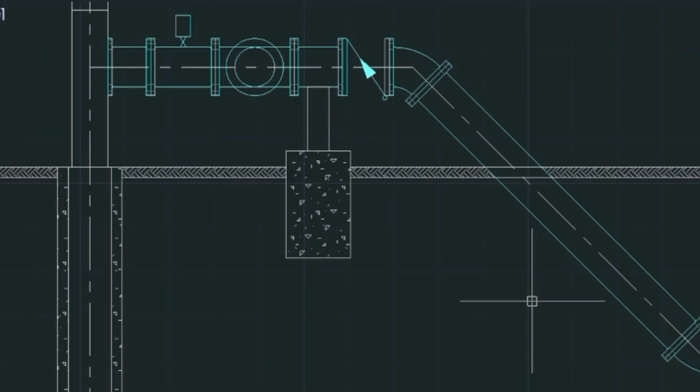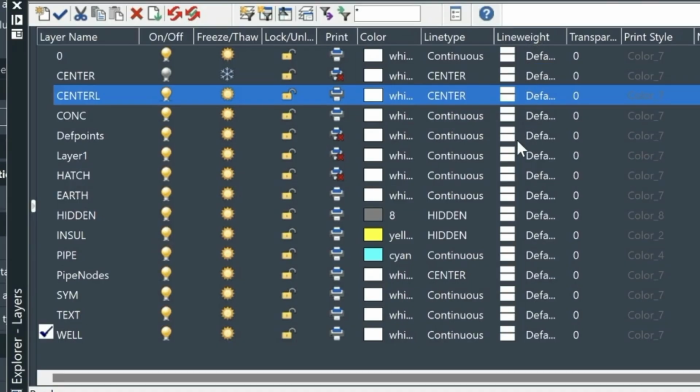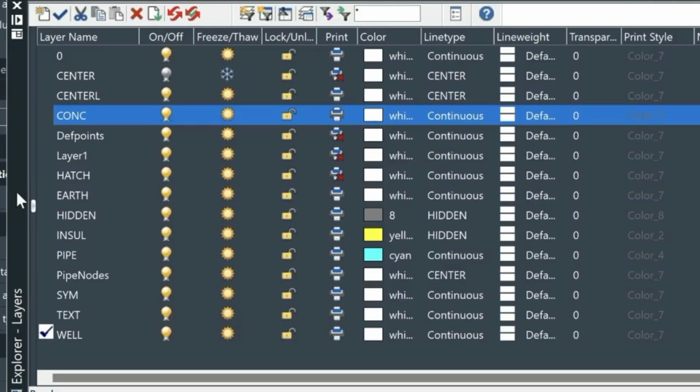Hi, welcome to part 3. In this part, I wanted to talk about line weights, annotative scaling, and dimensioning. You notice a column here called line weight. What we can do is increase the line weight for various layers. So in our layer manager, you'll notice a column here called line weight. So what you can do is increase the value how you need.